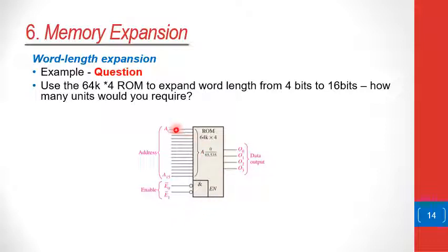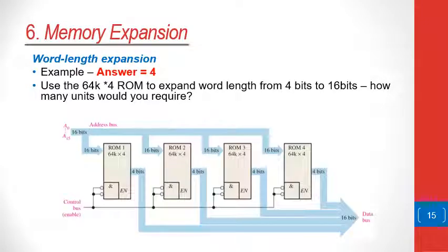If we want to expand this from a 4-bit word length to a 16-bit word length, the question is how many units would we require of these 64K ROMs? The answer to that question is simply 4, and the way in which you are going to configure the system of the newly expanded word length memory is that the